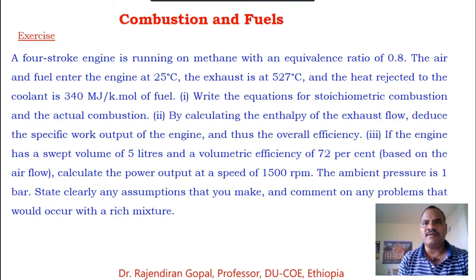Write the equations of stoichiometric combustion and actual combustion. Second one, by calculating the enthalpy of exhaust flow, deduce the specific work output of the engine and thus overall efficiency. If the engine has a swept volume of 5 liters and a volumetric efficiency of 72% based on the airflow, calculate the power output at a speed of 1500 rpm. The ambient pressure is 1 bar.